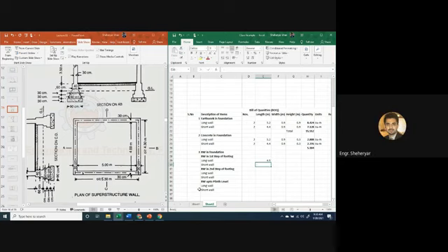And what will be the length of short wall? 5.3 minus 0.6. Okay, good. Numbers will be 2 and 2. Okay, what will be the width? Width is 0.6 and 0.6, and height is 30 centimeters, 0.3 and 0.3. I'll calculate the quantities later.